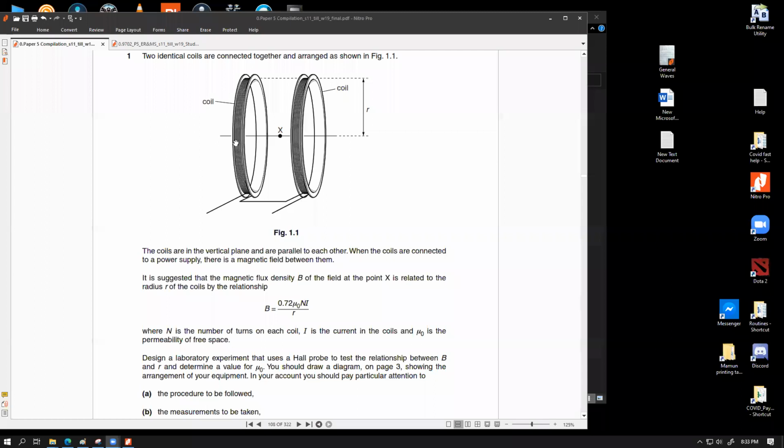Another thing that is pretty important is that, as the figure shows over here, the coils are not overlapping. So we should mention that as well, that we wrap the wire around the circular frame in a way that they don't overlap, and to make sure that they stay in that manner, we can apply masking tape, or you can say normal paper tape.